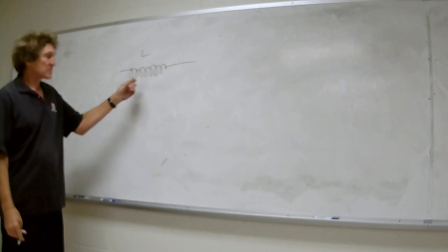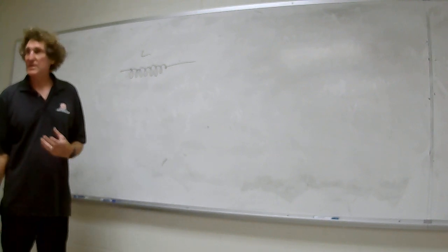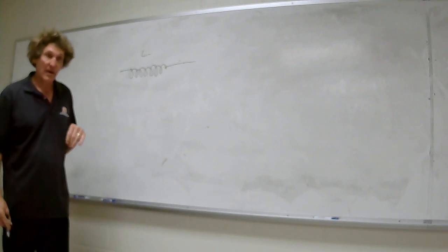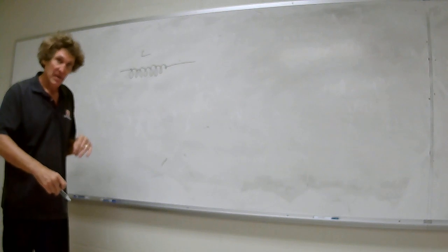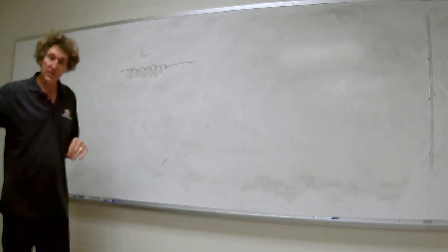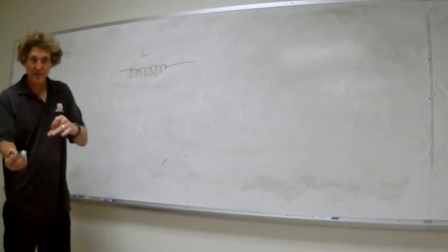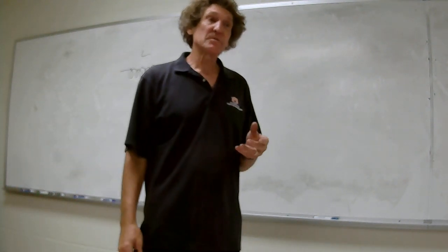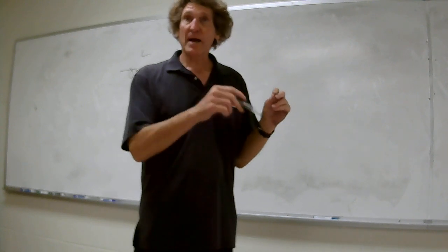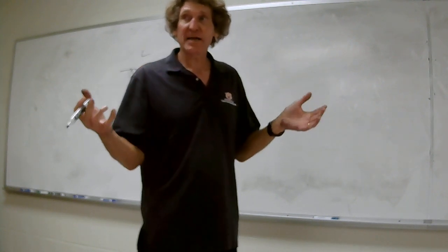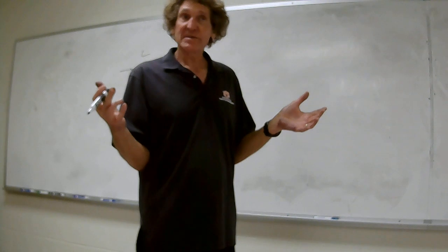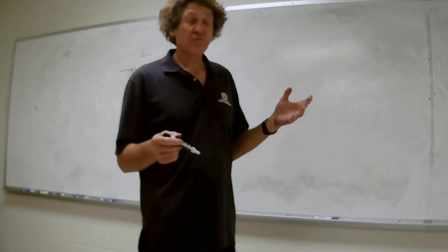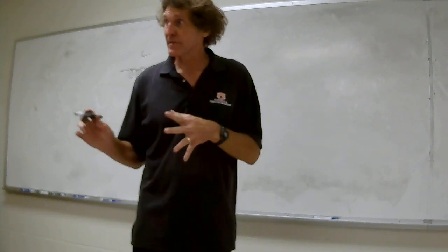Well, that's just called a lumped element representation of an actual inductor, whatever it could be. It doesn't need to have just a coil of wire. It could be a spiral of wire. It could be something where there's a contour of current that basically weaves around, and that would give you an inductance too. But what inductance is really saying is there's some current path that creates magnetostatic energy in a way such that it's linked to that inductor, and if you want to, you can get all that energy out. That's what it comes down to.